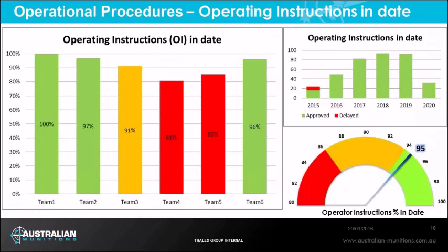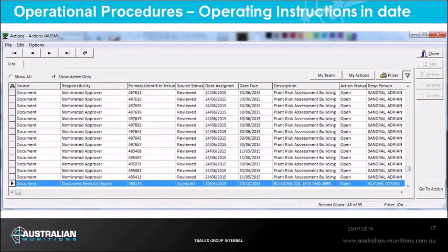A critical element of operating procedures is to ensure the procedures contain the correct scope. The process for review and approval of an operating instruction is tied to the layers of protection analysis study used for each production process at the Mulwala facility. The LOPA facilitator is a risk engineer that is also assigned as a reviewer of the operating instruction. In this way, each operating instruction review includes an independent review aimed at ensuring procedures contain the correct scope. The operating instruction expiry and review is managed in a centralised document control system, and the output from this system feeds the performance indicator.